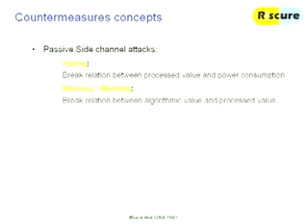With this type of countermeasure, you're trying to change the values that you are processing in your program without the attacker being able to know what you're processing. Basically, you mix in a random value in your algorithm and use that throughout, somehow masking the real operations that you're doing. At the end, you are able to reverse the effect and extract your real output that you're looking for.